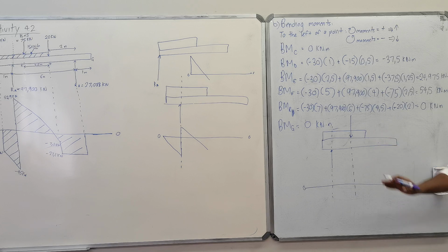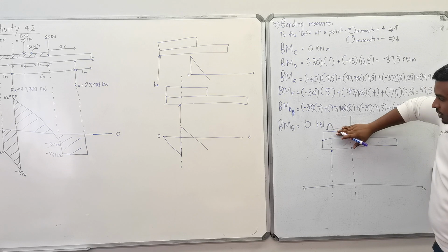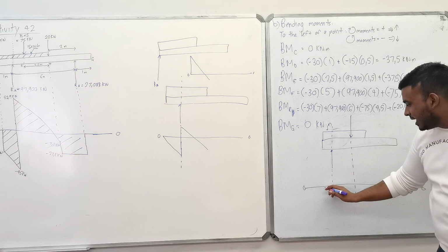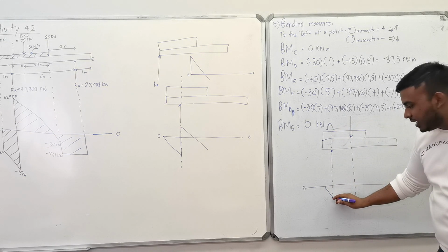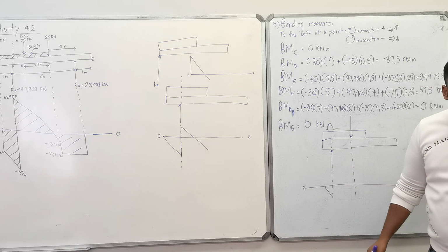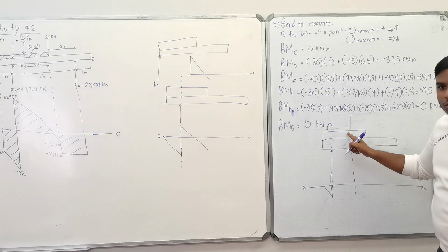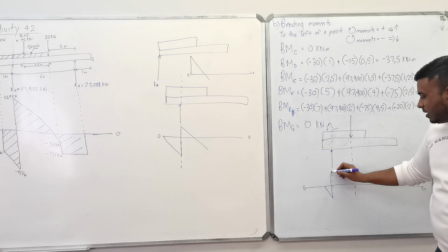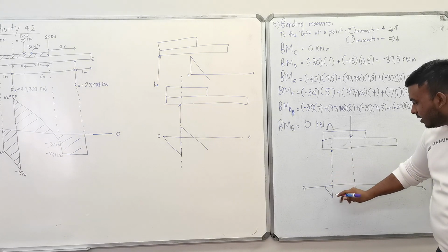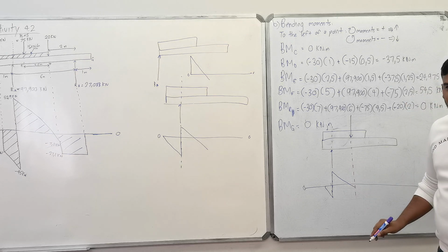Wherever there's a force, it should have a corresponding depiction on your shearing force diagram. So, here, remember it will be a downwards force from the uniformly distributed load. So your diagram, when it starts, because it's a distributed load, it's going to start like that. Then you have a concentrated load providing support, which will move it up positively. The distributed load is going to make it slope again, isn't it? That should slope again until this point here.